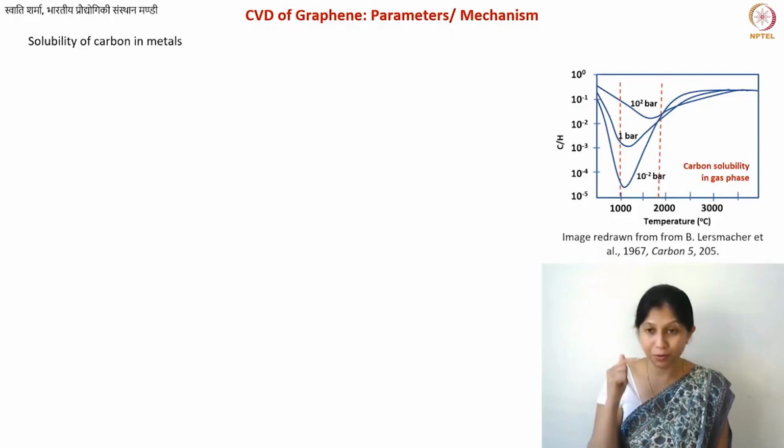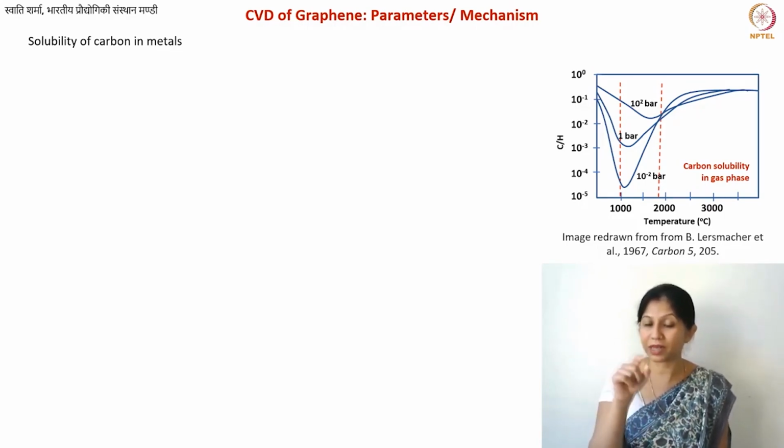An important thing is that as you change the pressure, how these curves change. And what is this minima, where you see the minima in this curve? For different pressures, again, you see different values of minima, that is your temperature value. That minima for your specific curve is the best deposition or collection temperature. Okay, C by H here is the ratio of carbon to hydrogen.